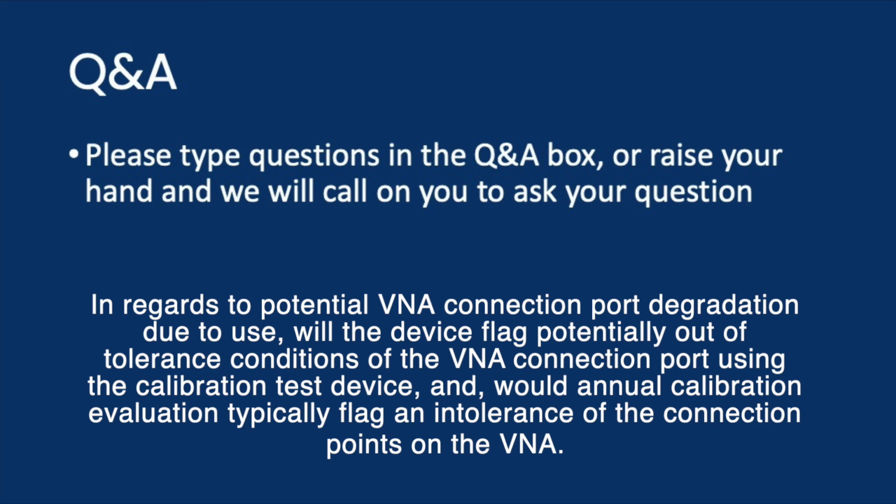So after we do the full calibration, then we reinstall, let's say, the open connector, and we compare what the instrument is saying that connector looks like with what the characterization data says that device actually looks like.